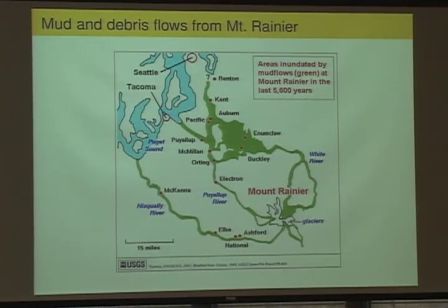And within those valleys, if you want to accurately model what might happen in such a debris flow, you need to have a very fine resolution grid to solve the numerical model of your model equations on. On the other hand, in other areas where there are higher peaks, you know that there's not going to be any flow at all, so you don't need much resolution at all.